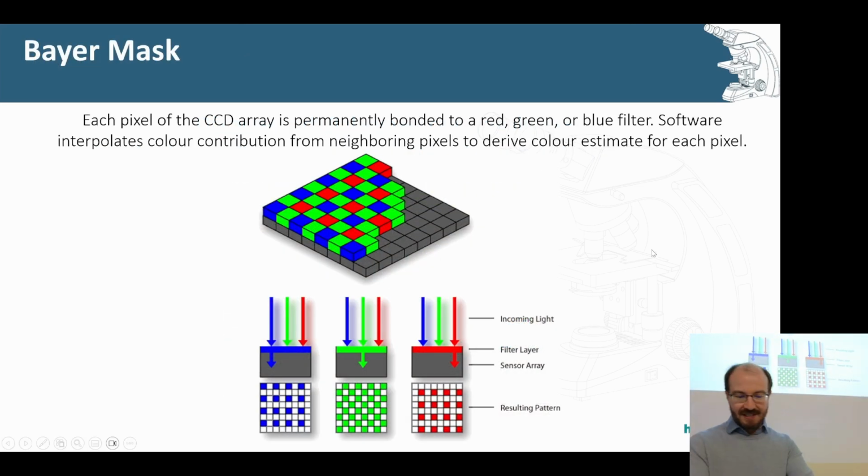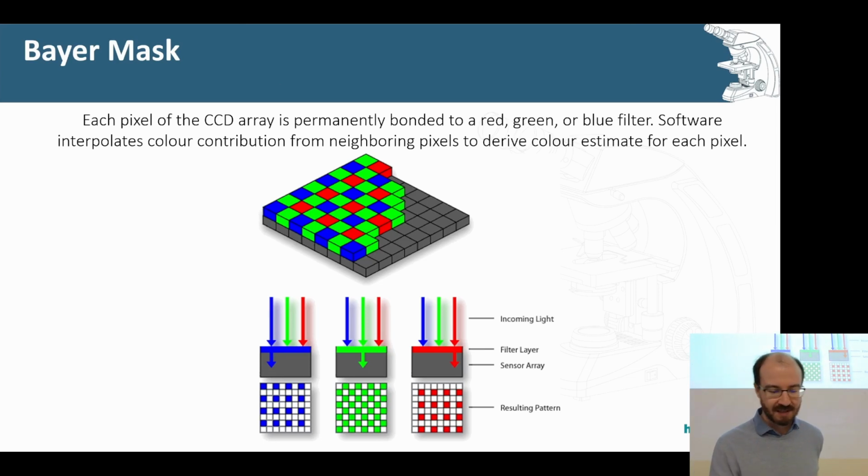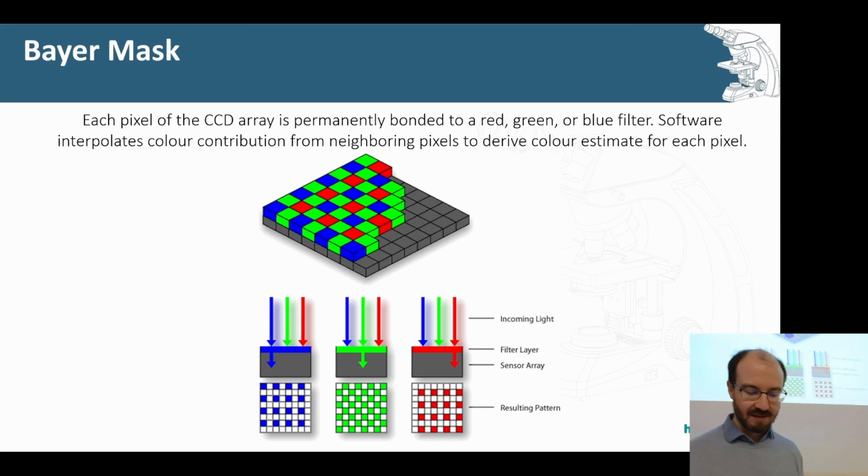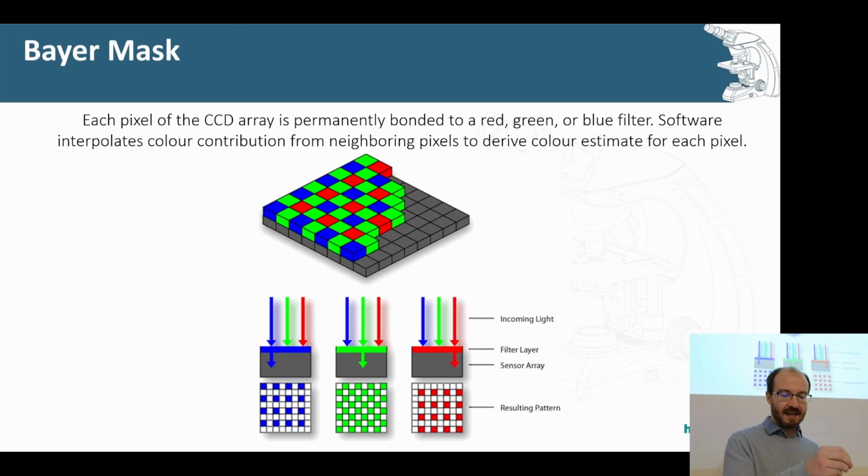Okay, so this is now a CCD sensor. This is a little bit old technology. Most modern sensors use CMOS, but the same principle applies. How the sensor is composed is you have all of these light-sensitive elements with a little filter in front of them. They essentially filter out different wavelengths of light which you don't want, and only capture the wavelength of light that you do want, but it makes it very specific. So it's only capturing exactly at the green, exactly at the red, or exactly at the blue. Or pretty exactly. There's obviously always some fall off there.